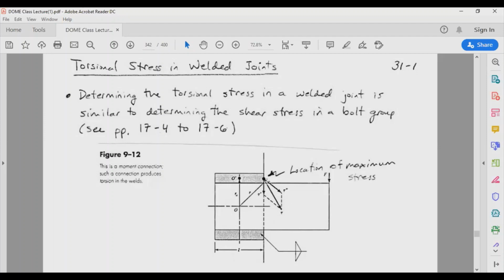So ultimately, you need to get that total shear, and one way to do that is you can decompose the secondary shearing into X and Y components. Here, obviously, it's going to be in the Y component, so you just add the Y components alone, and then you add the X components alone, and then you can do the square root of tau x squared plus tau y squared.